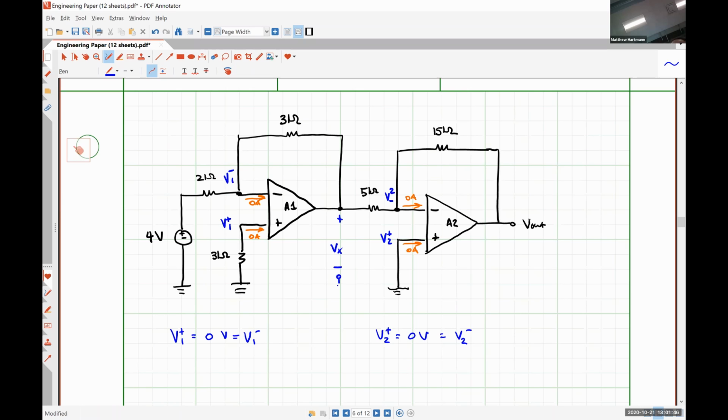So this is the voltage at the output node of op amp 1, okay, with respect to ground. So if we wrote a Kirchhoff's current law equation and said that this current plus this current is equal to 0, we would be able to determine what that voltage Vx is, despite the fact that the other operational amplifier is connected to it.